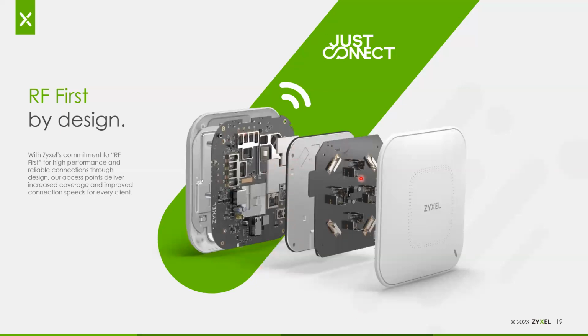The other thing we do differently here is on most of our access points, we do not put the antennas directly onto the PCBA. We have a separate board that's isolated here with a separate little shield to help isolate it from any EMI issues from the main board. So these are separate, and it just provides that much better signal to noise ratio out in the real world.